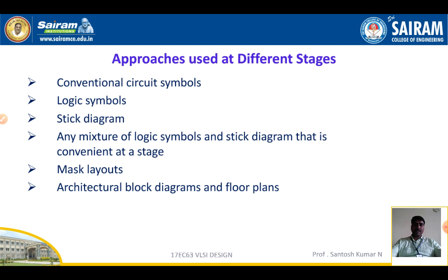For this logic symbol, we are going to write a stick diagram which will be convenient for designing a layout which is used for fabrication. These layouts are again floor planned. Floor plan is nothing but placing of different components at nearby places which will become convenient or easy for routing purposes.